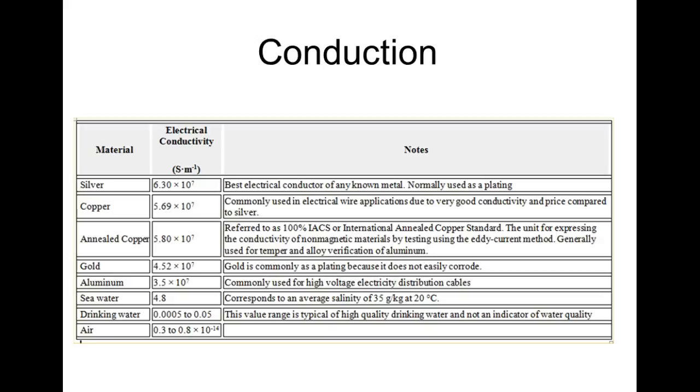For years and years, silicon, which is a semiconductor, was the main building block for all integrated circuits. So all your processors, all your computers, all those little square blocks you see inside a computer could not use copper because silicon would eat up copper. If we tried to put conductors on the silicon that were made out of copper, it would eat it up. So for years, all the conductors inside of every IC you saw were made out of aluminum.